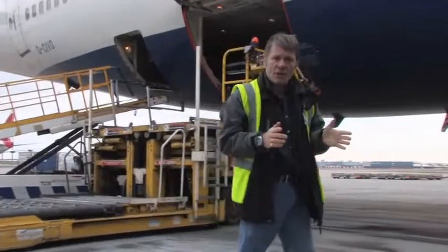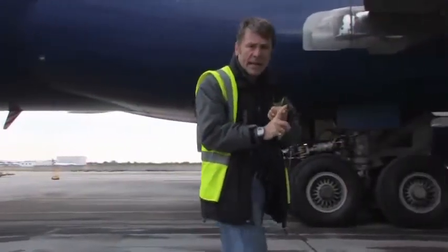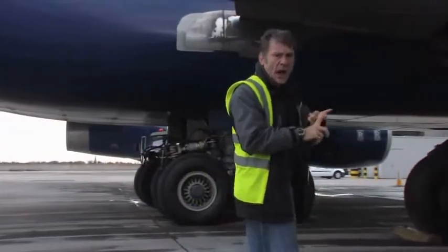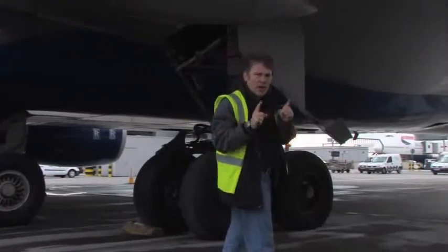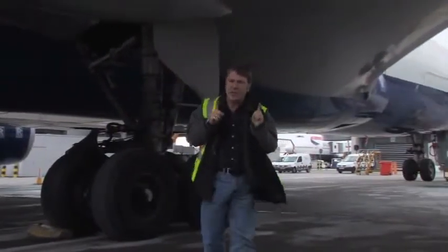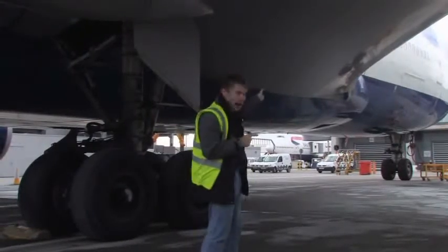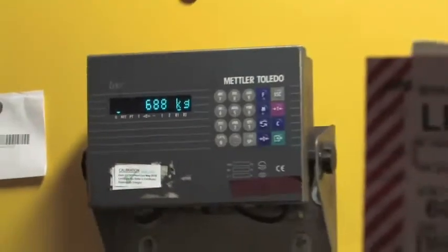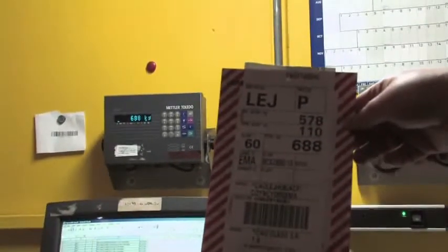Now, if dangerous goods are carried aboard the aircraft, it's important, one, they're labelled correctly, they are securely stowed, and they're stowed the right way up. In addition, something called a NOTOC, a notification to the captain, is going to be given, and that's going to be given up there. Dangerous goods must be packed, loaded and secured in the proper manner.